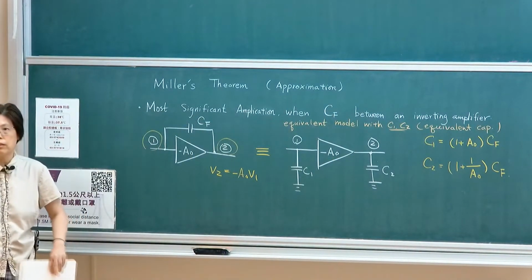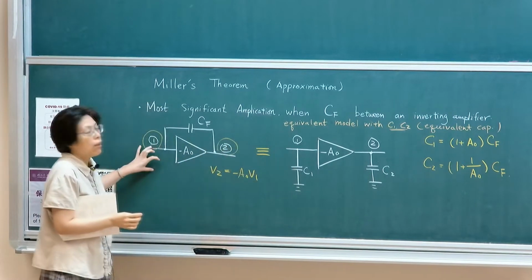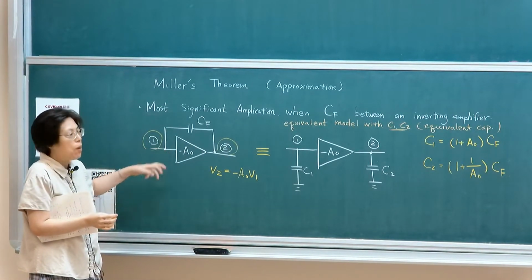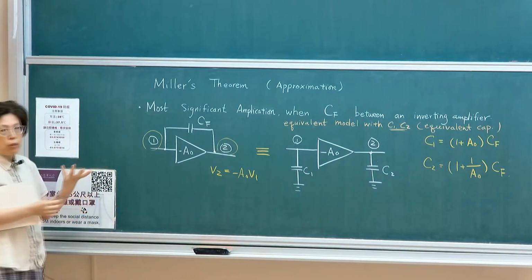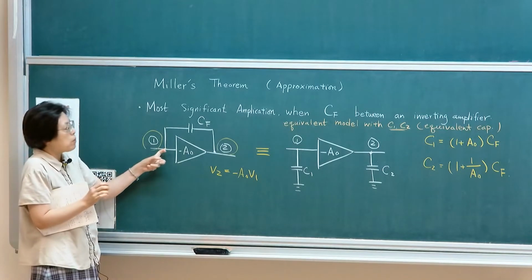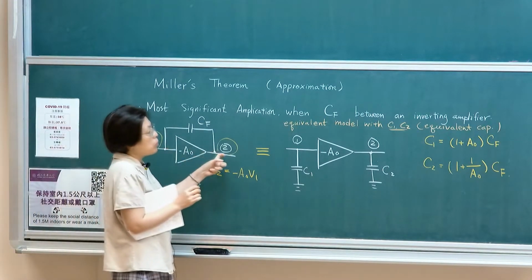How does one determine these equivalent capacitances, how do you use C1 to represent the hard-to-drive point of terminal 1? We use our derivation of equivalency in terms of the response of voltage and current at terminal 1 and terminal 2.